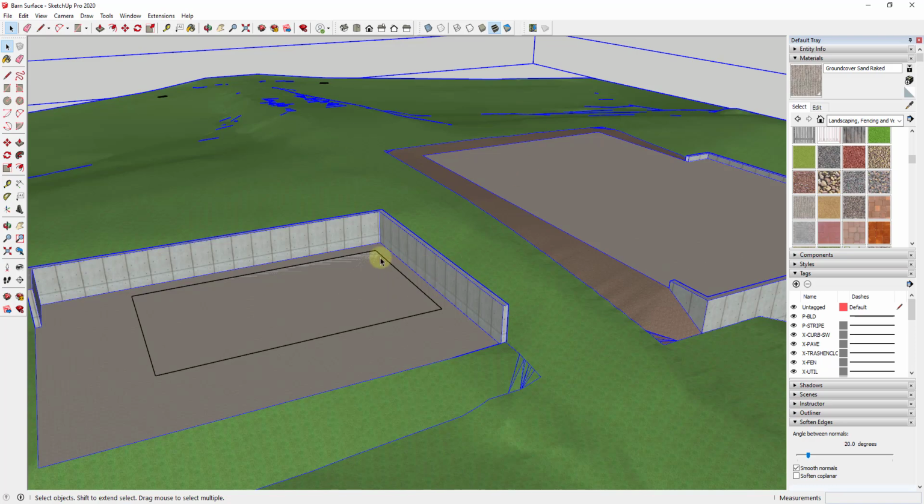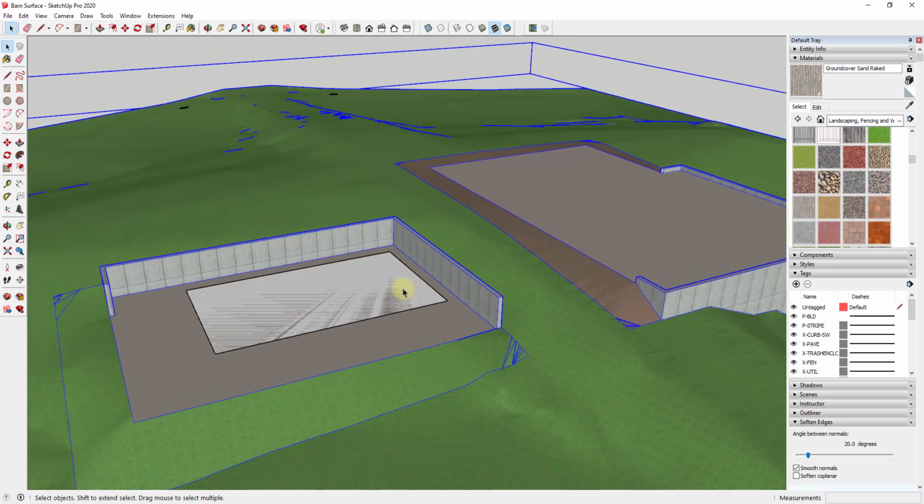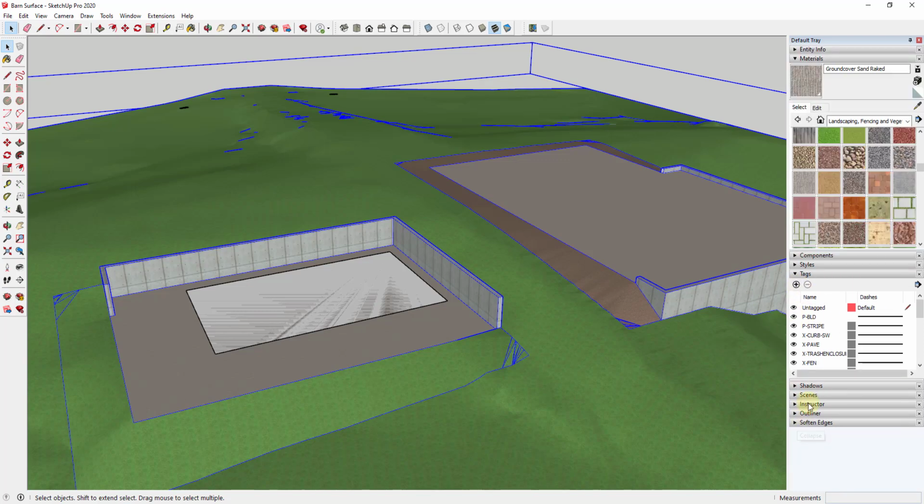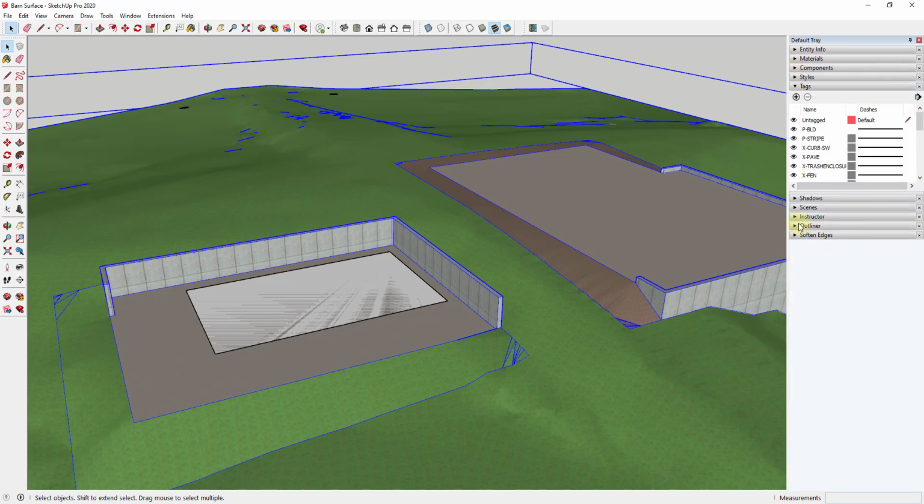So with my whole site, now that I have the base of my floor plan placed, I'm actually going to turn this site off. I'm going to create a working view here where I can do that. I'm going to come through and clean up some of these tags in the CAD file a little bit later. I'm not going to worry about them for right now, but I want to make sure that I have an organizational structure that actually makes sense. This is actually going to have to do both with your outliner as well as with your tags.